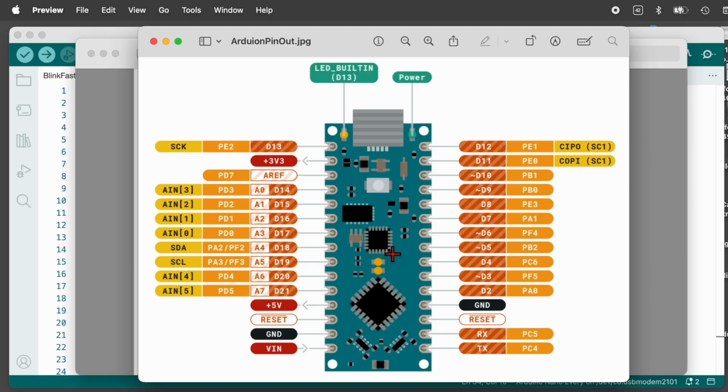And so you can run your program even when the USB is not connected, as long as you're supplying voltage in down here. There's a pull-up resistor internal to the board on this, so we can just leave that unconnected and it will be high at all times. And if you want to manually reset the Arduino, that is, restart your program, you can just push this little push button on the board.